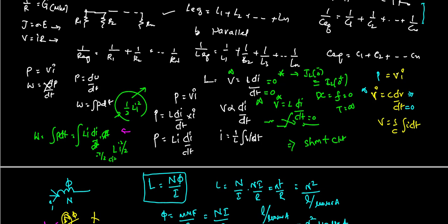Whatever the voltage before the switching action must be maintained after the switching action for some time. That means it acts as a voltage source for some time, at t equal to 0 plus. After the transient disappears, it comes to steady state and the normal circuit comes into the picture. If you solve the transient, you can understand, no problem.